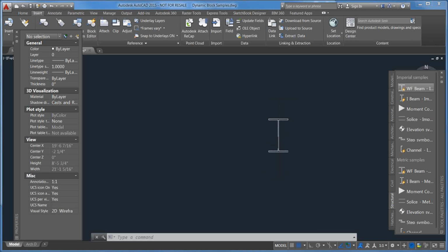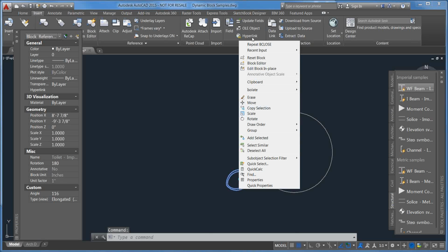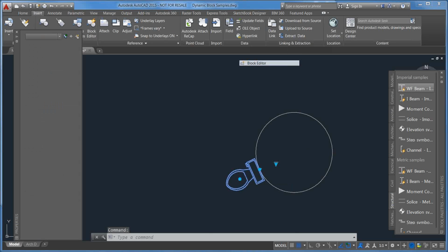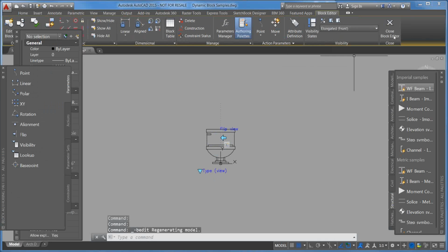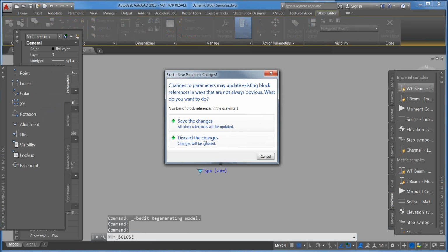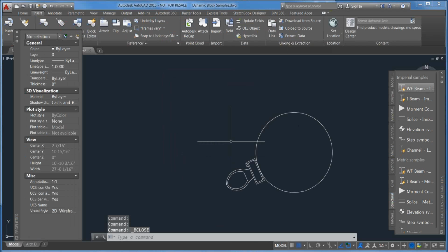I'd say give it a try with your rotate parameter. Do I have one here? I could quickly try something, but it would take a little experimentation. I've not actually tried that myself. My hunch is yes, you can make that happen, but what I would probably need to do is also assign a constraint to the text, or perhaps constrain the text to something in the drawing, like a line, which is then constrained to be horizontal.